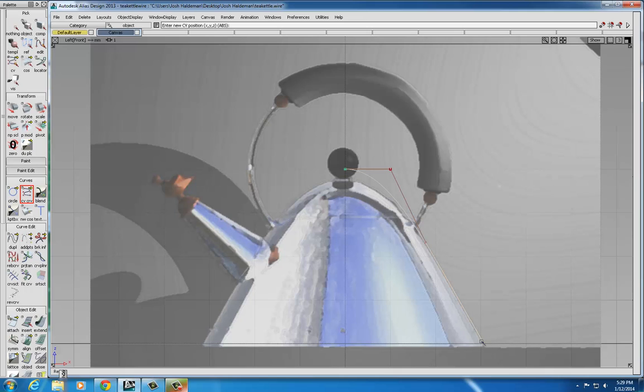When I place that last point there, you'll notice that I've placed a total of 4 CVs. This is the first time we're able to see the curve. That's because this is a degree 3 curve, and I have to place at least 4 points for the curve to be able to pop in. Once I've got that fourth point in, though, the curve itself snaps in, appears, and then you're able to make modifications to the line itself.